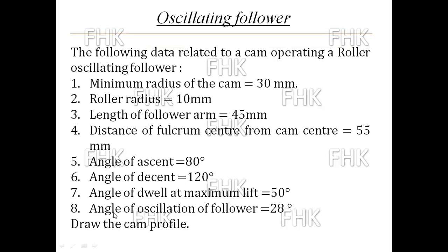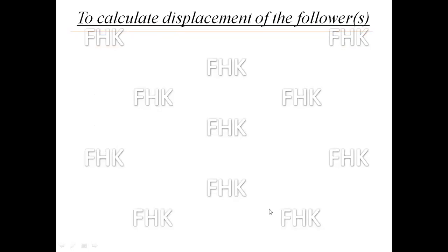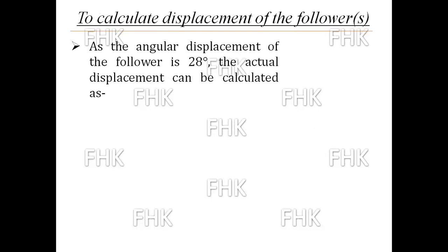But the angle of oscillation of the follower is given as 28 degrees. That 28 degrees we have to convert into displacement of the follower in mm.